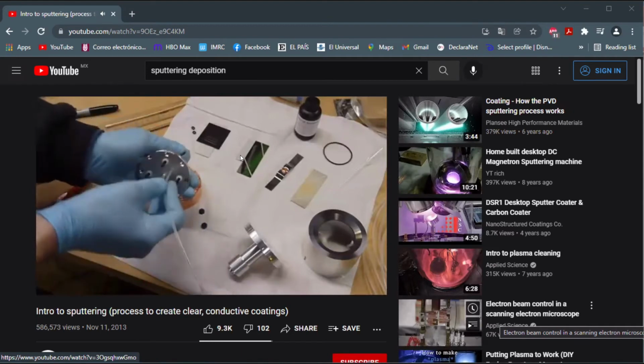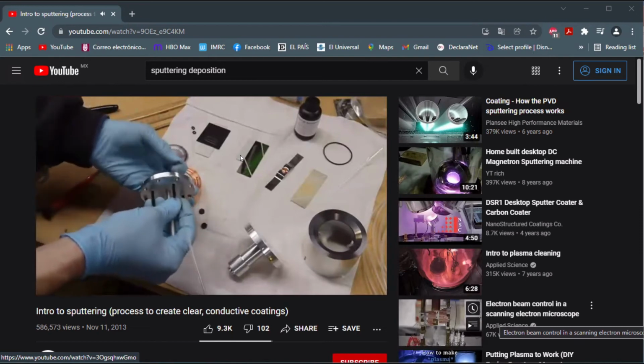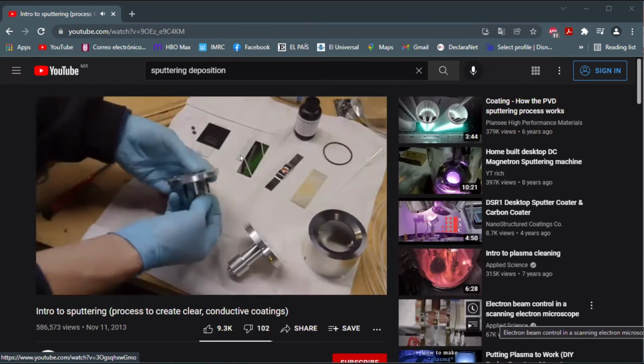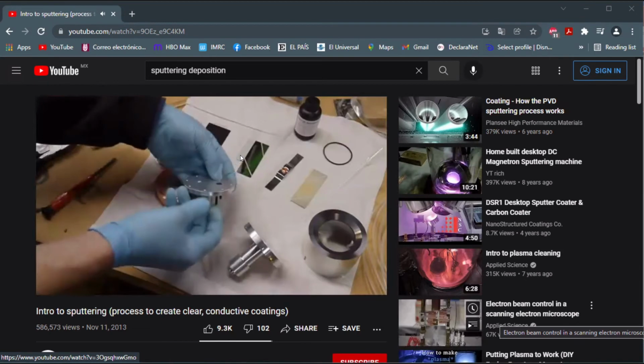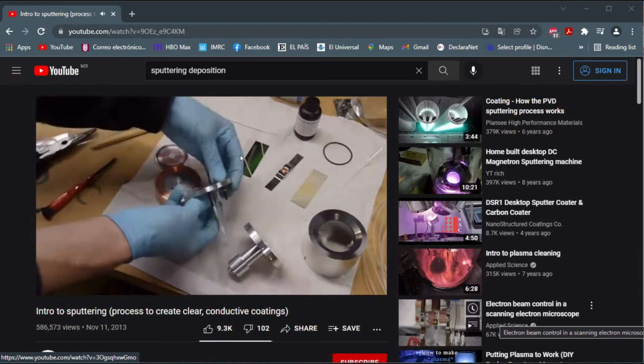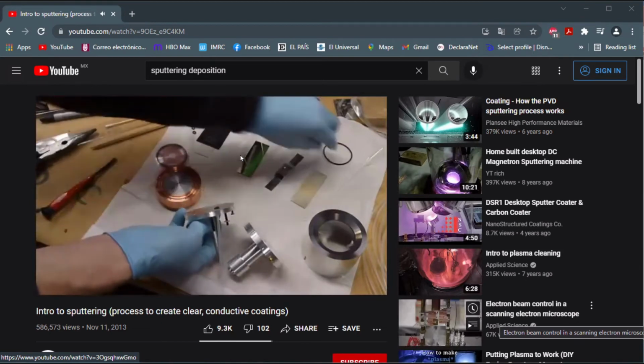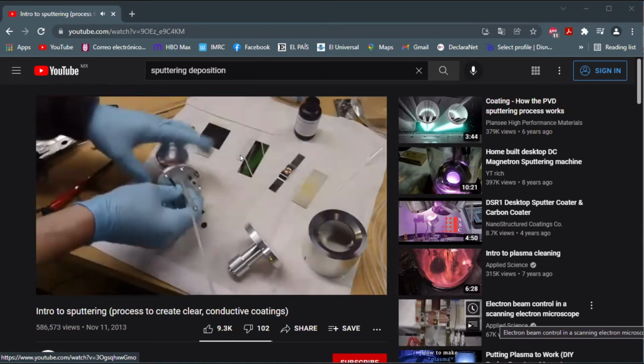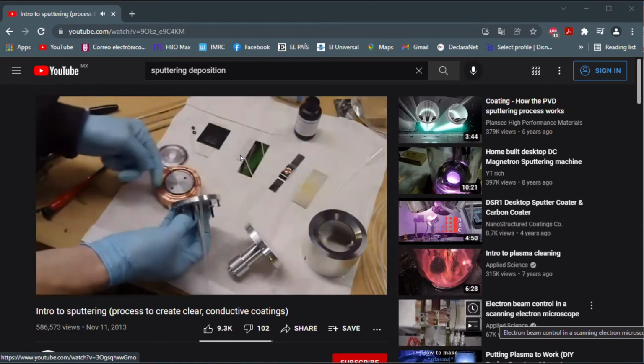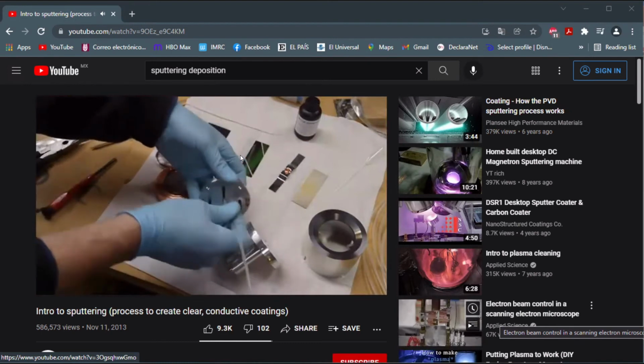And the idea with that would be, this is a sort of a Teflon hose. It's actually a plastic called PFA. With an O-ring on like this, the hose can be sealed up to this, and then with an O-ring in the right spot here, this whole thing closes up and I can actually pump water through the copper block.